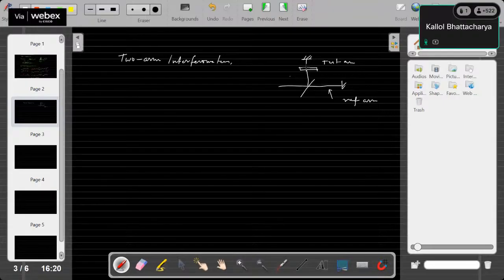So the light from the test arm and the reference arm are made to interfere on a screen. Of course, these days you do not have a screen, you have a CCD or CMOS device, a digital recording device. And you can see the interferogram on the screen. It is not only sufficient to see the interferogram, but it is also necessary to interpret it. From the fringe analysis of the interferogram, we can easily find out if there is any defect in the flat plate we are testing.